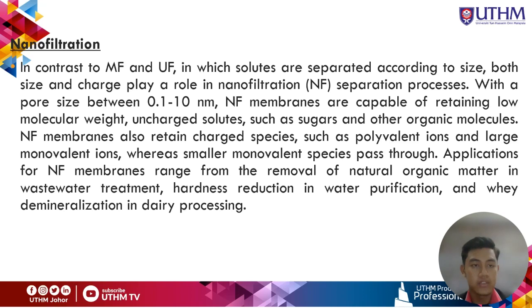For nanofiltration, in contrast to MF and UF, in which solutes are separated according to size, both size and charge play a role in the nanofiltration separation process, with a pore size between 0.1 to 10 nanometers. Nanofiltration membranes are capable of retaining low molecular weight uncharged solutes, such as sugar and other organic molecules.